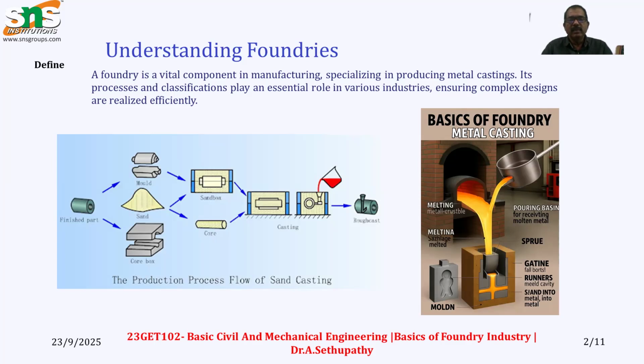First of all, we make a mold. First, we make the pattern. The pattern is the masterpiece of the product we are going to manufacture. This pattern can create an enormous number of molds. The mold is the cavity, the impression of the pattern. The impression is created in the molding sand, which is covered by boxes.